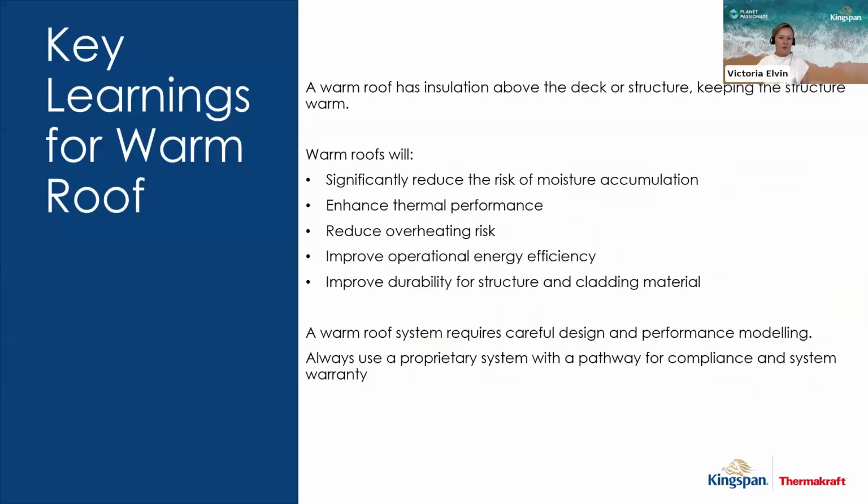So today we've learned that a warm roof has insulation above the deck, keeping the structure warm. It can keep the structure drier, giving more durability to the roof as well. It significantly reduces the risk of moisture accumulation and enhances the thermal performance of the roof. It can be ideal where the circumstances are not suitable for cold roof design. It provides a functional and highly efficient roof design.